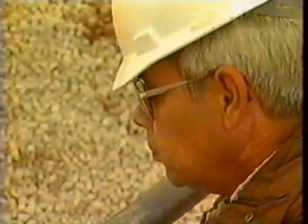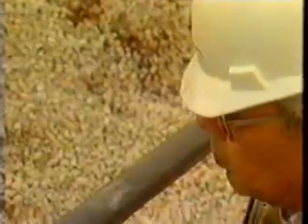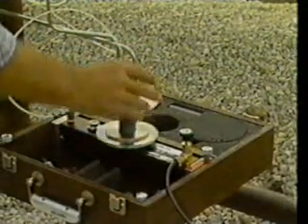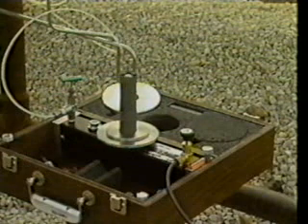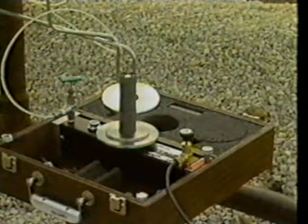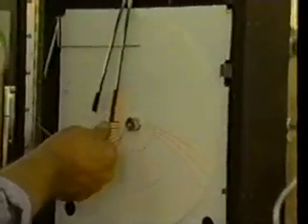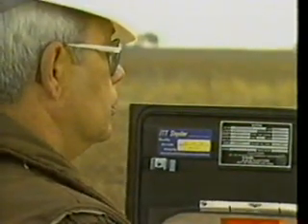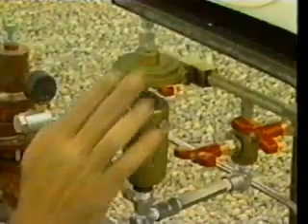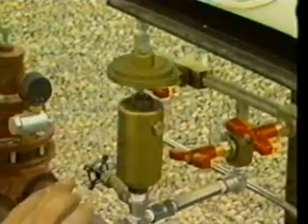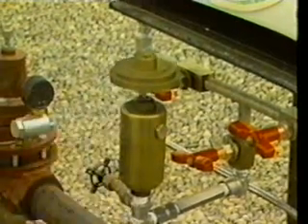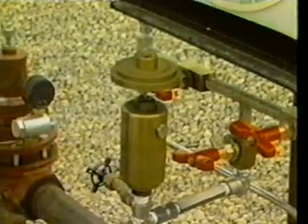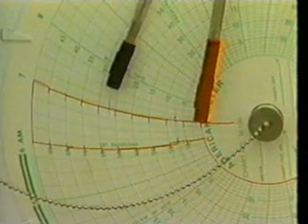Check for piping leaks. Check the differential element for calibration at a minimum of 5 points, both up and down the scale. See that the inking pens have the proper pressure against the chart, that the pens are in good condition, and the ink flows properly. Check the temperature recorder. Using the dead weight tester, check the static element for 0 according to contract requirements. Also check the differential element for accuracy and arc.